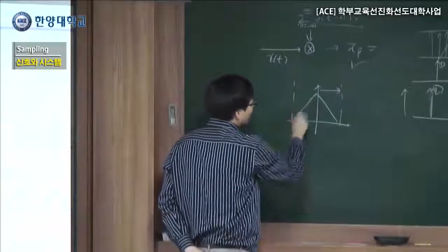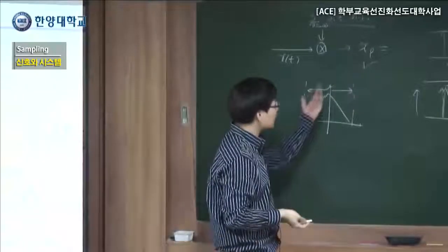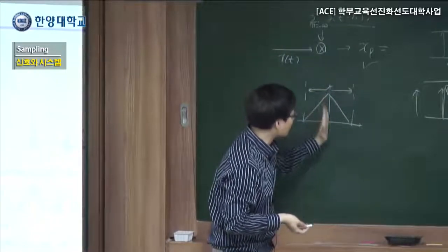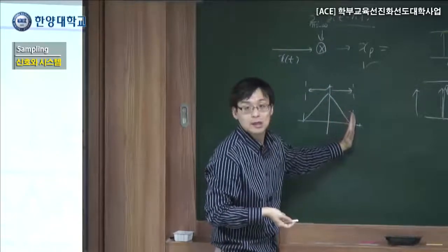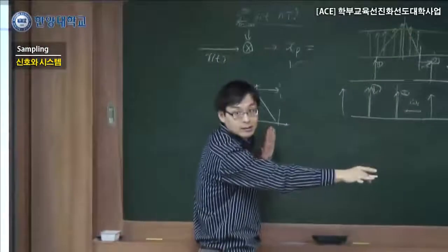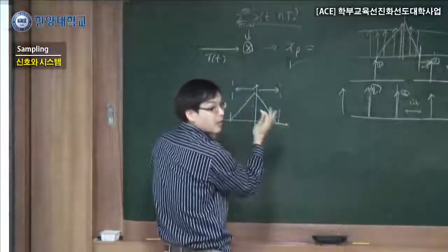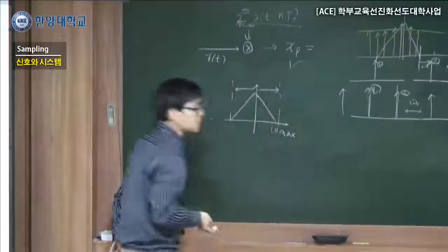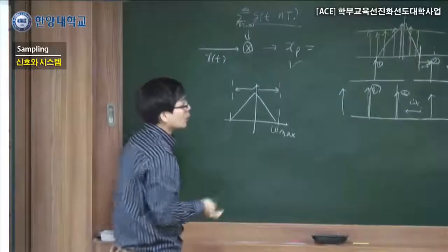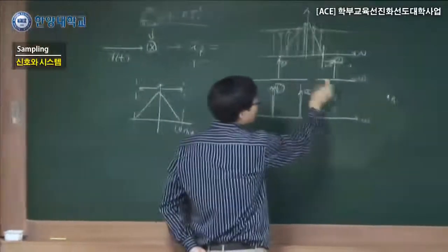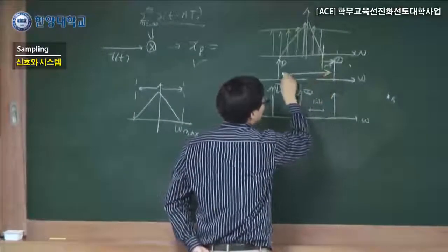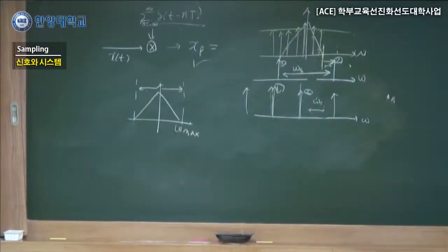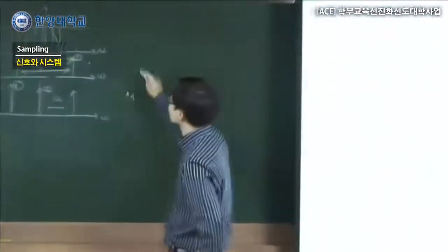Of course, if this is real, then we don't have to worry about that, but it sometimes has a minus sign. What this says is that this value goes from 0 to a certain frequency and doesn't have frequency larger than that. So we refer to it as a band limited signal because we can define the maximum band. What is the maximum frequency of this? And from here to here, what is the spacing? We define it here as omega s. What is omega s?